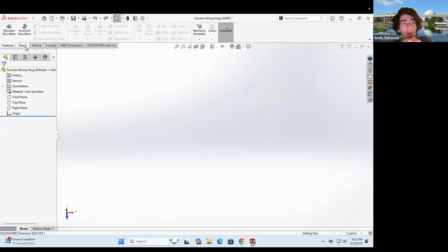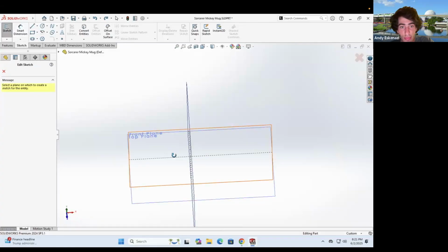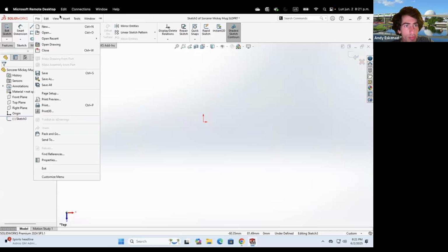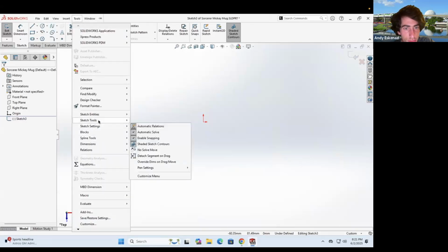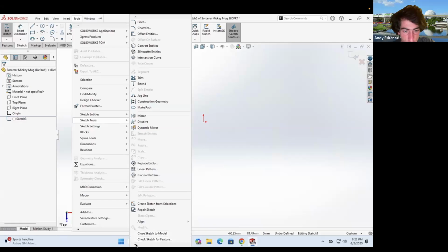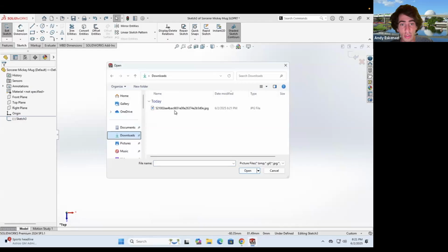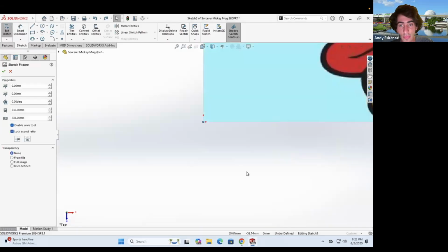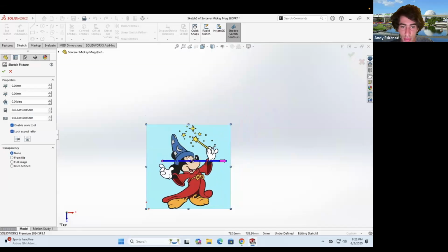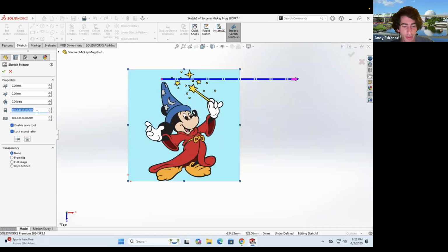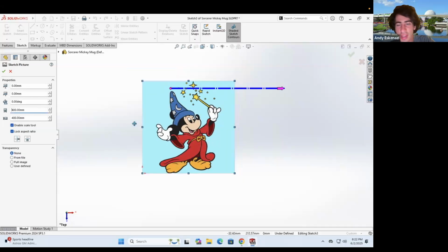Now I'm gonna come here. So we're gonna go to sketch, top plane, and I'll go here to tools, sketch tools, and then sketch picture, which should be, there we go, down here. I click in there, and where it says downloads, I bring this picture, click on open, and boom, here we got our sorcerer Mickey. Now, I like to think that dimensions honestly don't matter, like how big you see the picture is 400, I can make it like that. The reality is that we can always scale objects at the beginning or at the end, so I'll just leave it like this. I'll click OK.